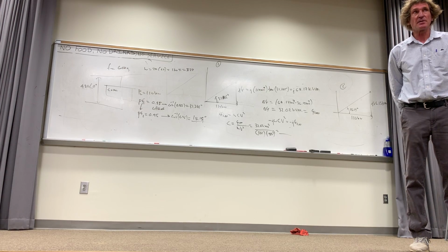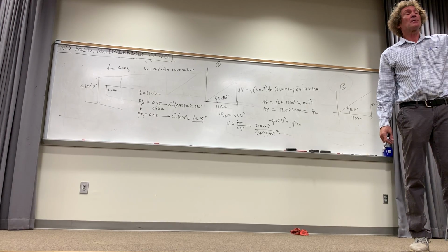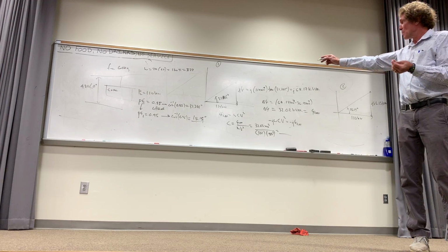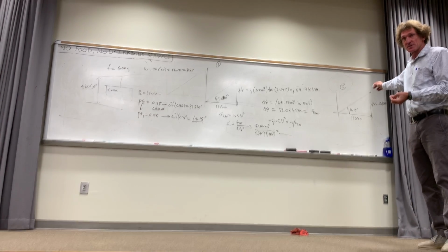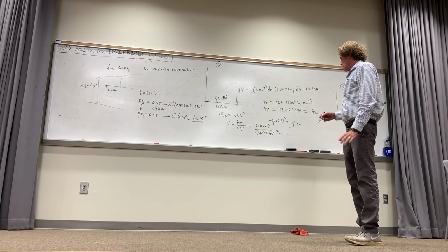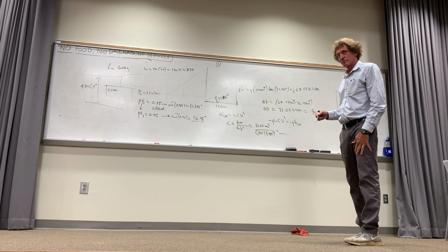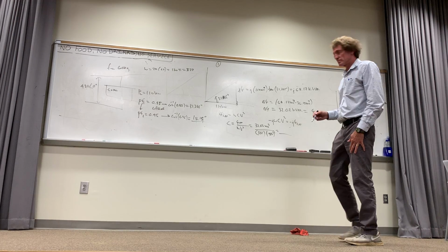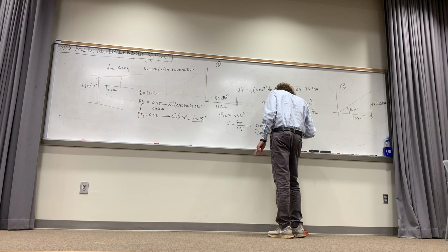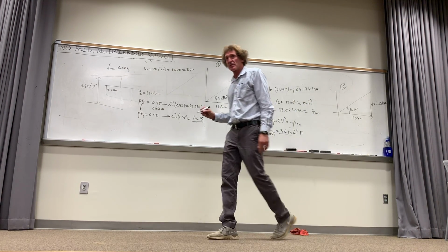Do y'all follow me on this? We're just calculating reactive power on the capacitor to get the size of the capacitor. We're given the reactive power actually. We got it from going from that power triangle to this power triangle reduction. Correct, class? So what is this value going to be for C? The 480 is squared, remember. 3.69 times 10 to the what? All right, and the units of capacitance are farads. I want to tell you it's a fairly large capacitor.